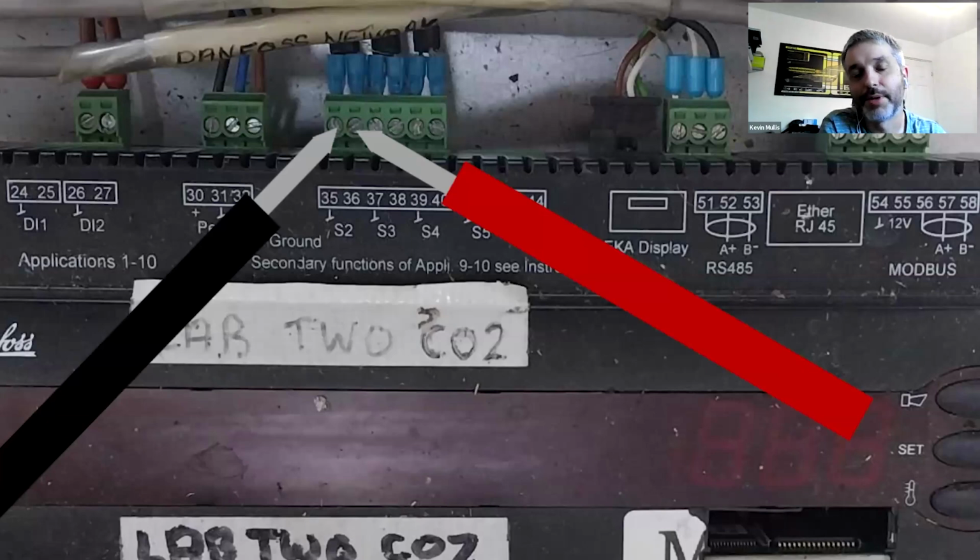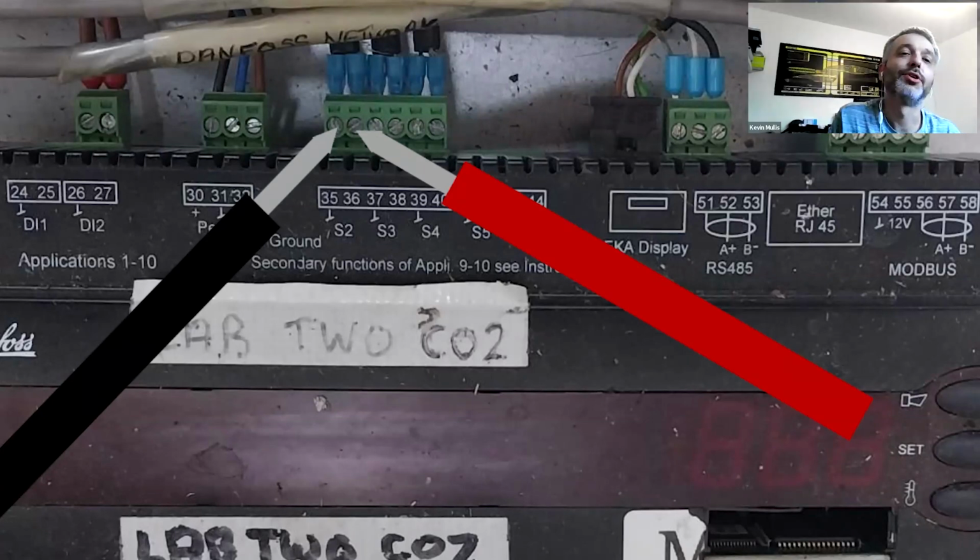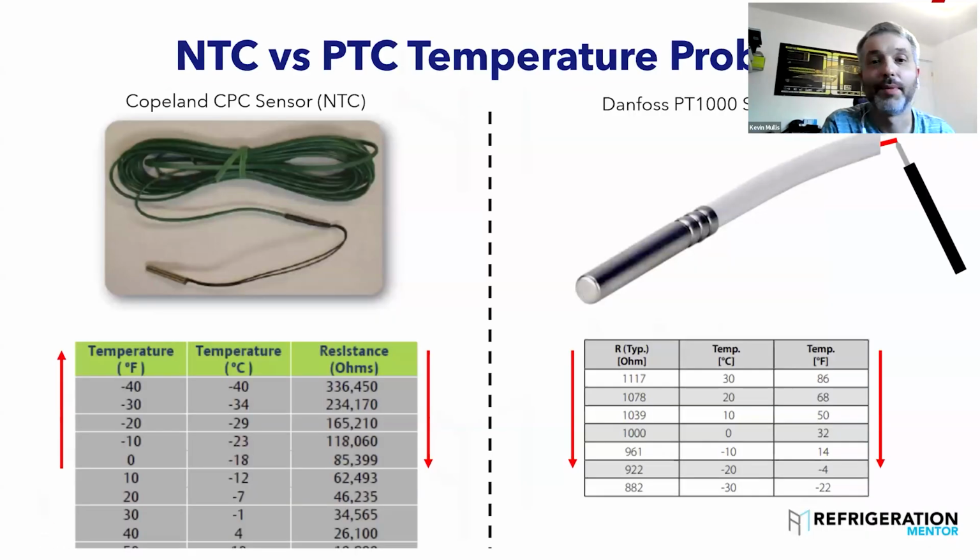So resistance range is pretty tight on those. I think we have got a slide somewhere with the resistances for the probes on, Trevor, haven't we? Yeah, I'll show them. But yeah, you can look that up in the field as well. I think there you go on the right hand side, PT1000 probes. It's 1,000 ohms at 0 Celsius is your reference point for it. But you're talking a really tight resistance range.